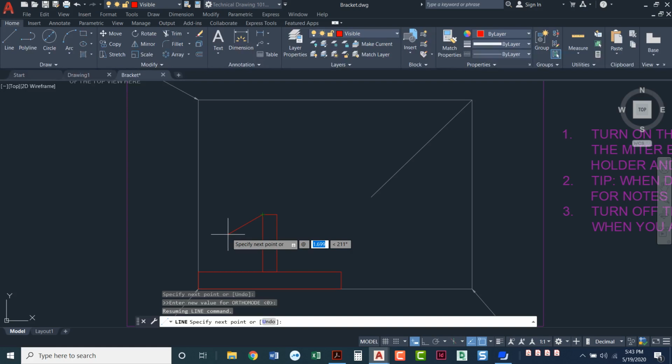We're going to go negative along the x-axis, 1.20. So relative to that point that I just clicked, we're going to go to the left, or negative 1.20 on the x-axis, comma. We're going to go down 0.25, so that would be a negative 0.25 on the y-axis. Make sure you type in the @ symbol, negative 1.20, negative 0.25, and now I can just snap right here to this corner. I'm done with the line command. I'll press enter.